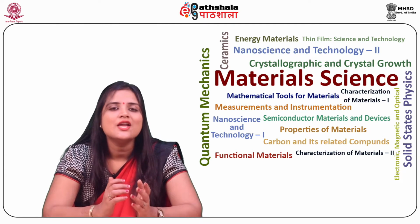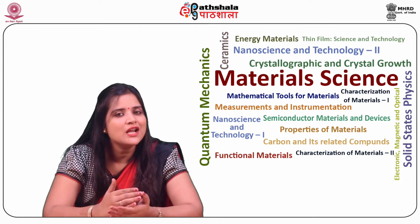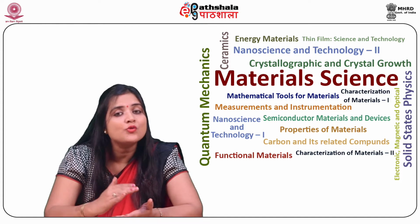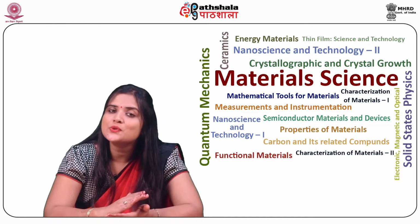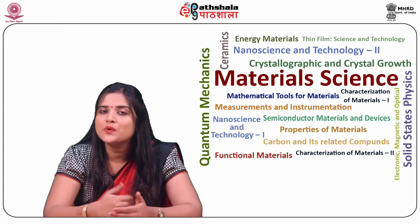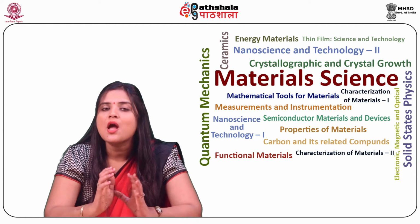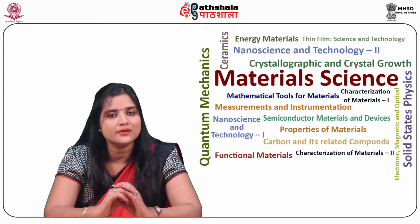Negative feedback is used in amplifiers as it stabilizes the gain, increases the bandwidth, increases the input impedance, and decreases the output resistance. Negative feedback also reduces the variation in output of an op-amp due to variations in temperature and supply voltages. We will be studying about op-amp in negative feedback configuration over here.